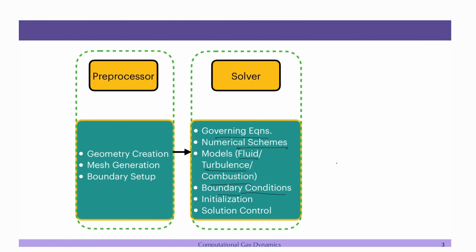So, you have the boundary. I discussed, let us say this is a flow over a turbine blade. So, this is a boundary. Now, here you can apply the pressure inlet or you can apply the velocity inlet. Here you can apply pressure outlet or you may apply non-reflecting boundary condition. So, even if you have physically made this boundary, what should be your boundary condition? That is a very important question, which can give you the correct flow, right. So, that you have to decide.